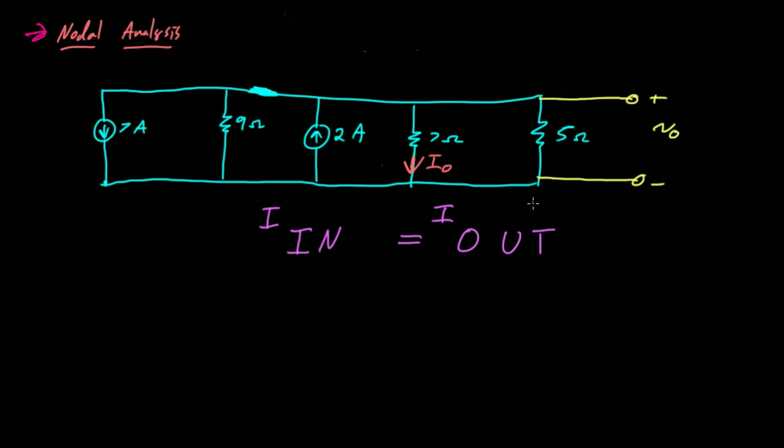So I've got this circuit up here, and the first thing I want you to think about is just how many nodes do I have in this circuit? And remember that a node is essentially a wire in this diagram. It's a point where everywhere on the node, the voltage is going to be equal. So if I look at this, I can see that I have got this whole thing up here. Let me color this in. So this whole part of the circuit is one node.